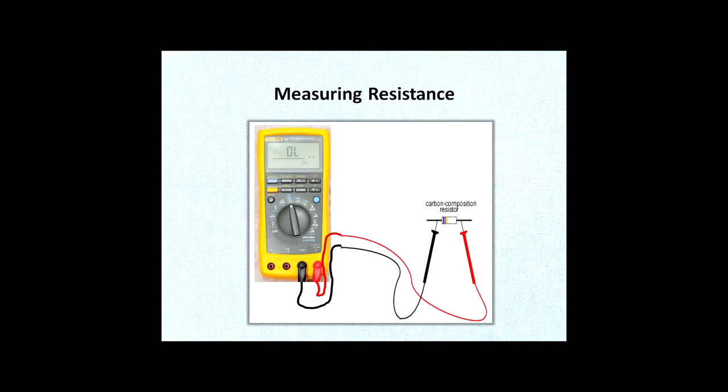Okay, now measuring the resistance. You basically put those probes against 2 leads of this component. Make sure you do not hold that with your fingers. You hold your probes right here. Do not touch the metal parts, because then you're putting your own body resistance in parallel with this resistor. Your body's resistance is not infinite. We do have resistance between our hands, okay?